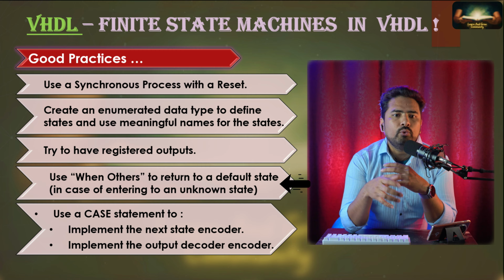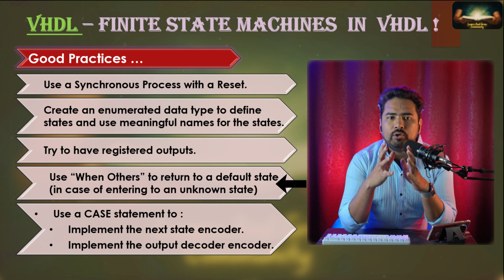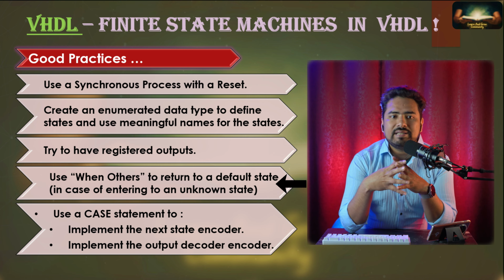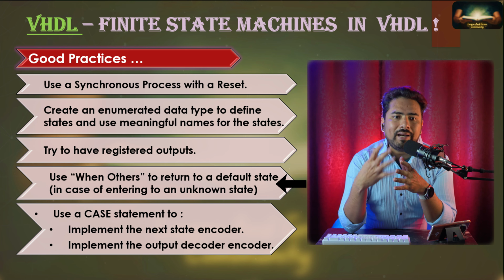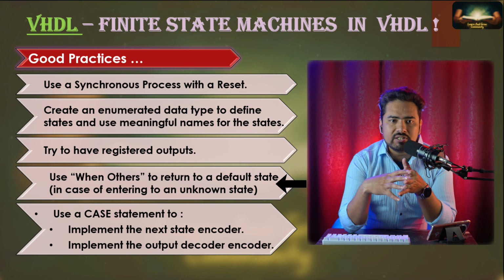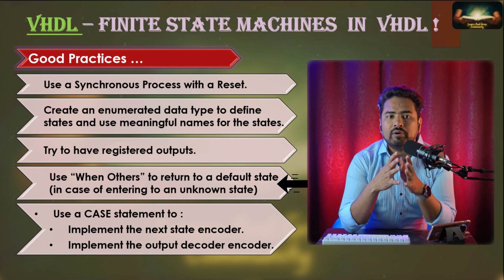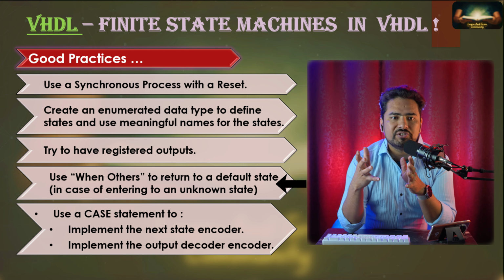Finally, always include a when others condition and use that for your reset transitions as well. And it will protect your design from logical glitches or hardware glitches or real-life unwanted conditions.